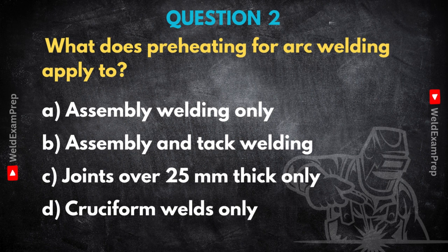But here's the often overlooked part. Tack welds. People sometimes think of tacks as just temporary little stitches, but tack welds are actually the first welds in the assembly. They experience the same thermal shock, the same cooling rates, the same stresses as the main welds. If a tack weld cracks because it cooled too quickly, because it wasn't preheated when it should have been, well, you've just introduced a defect right at the start.